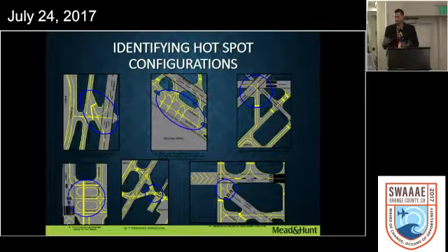And then trying to remove the Y-shaped taxiways for the same reason, just to avoid pilot confusion and in simplifying access to and from the runway environment. Again, to avoid confusion and increase safety.